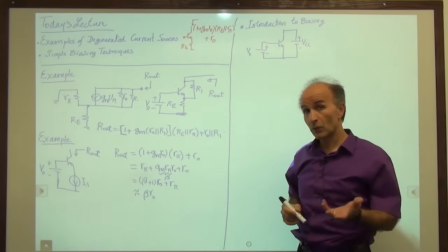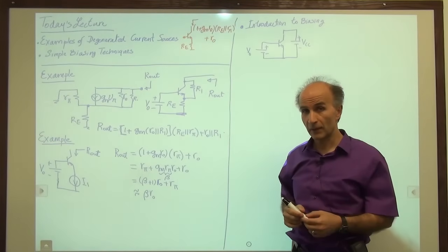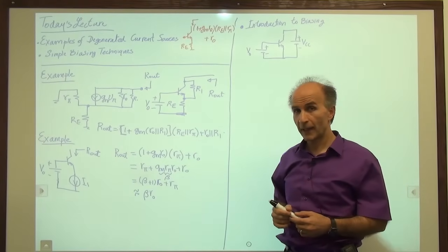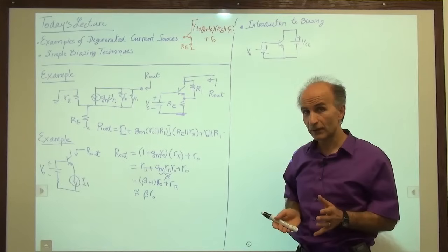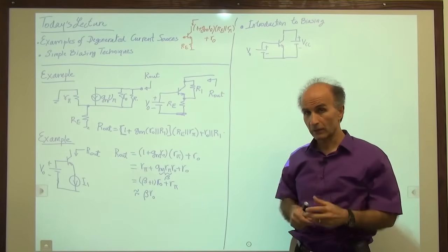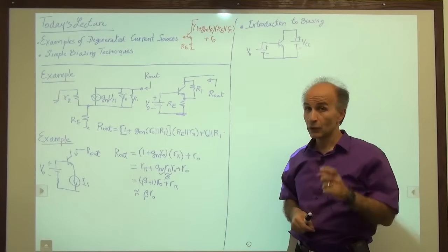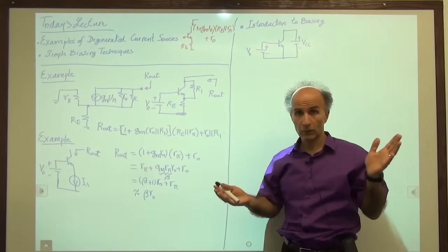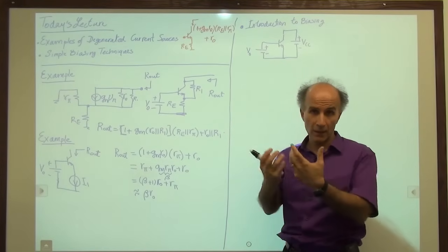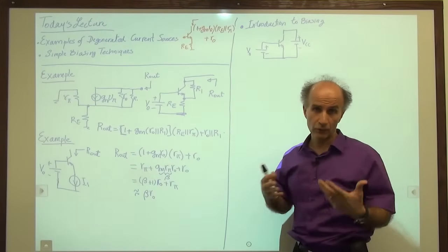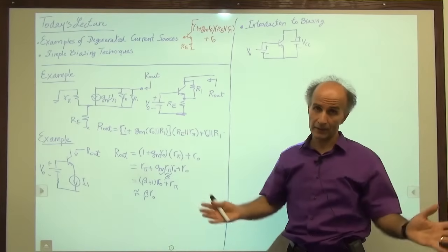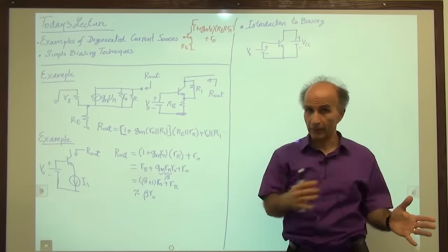Well, we know something from basic circuit theory that helps us. We know that if we have a resistive divider, we can take a larger voltage and divide it to get a smaller voltage. Now, we do need one reasonable supply voltage, battery in the entire system, right? The system needs some sort of energy from outside to do amplification, etc. So we have one battery for this entire system consisting of many amplifiers.